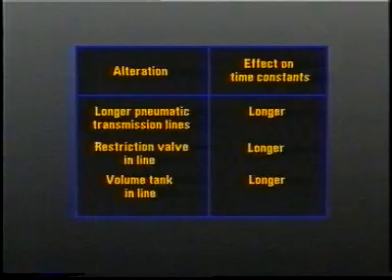And volume tanks. Volume tanks are a very effective way to add more lag in certain situations. They should not be added in a feedback sensing line, since this would interfere with feedback and result in poor control.